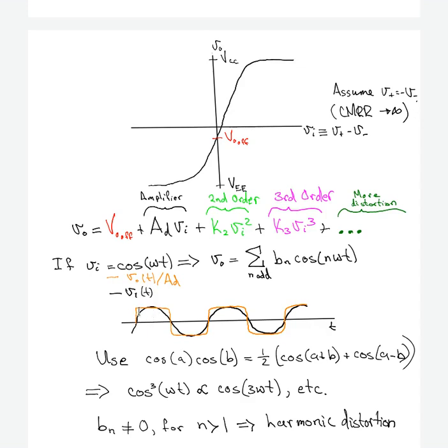Now, when you have a voltage like this kind of squarish wave, it is a periodic waveform, and it can be written in a Fourier series as denoted up here. To get an idea how that might work, the n equals 1 term is somewhat like the input here. It's black, like the black input. The n equals 2 term is not present in this square wave. The symmetry doesn't allow that to happen. But the n equals 3 term is present in this square wave.